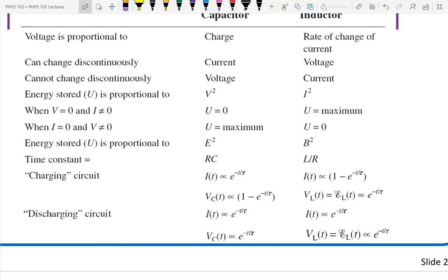So you have a capacitor that's really charged up. As some of you saw, you take that capacitor and you short across it once it's charged, and what happens? If you short it, what's the resistance between the two ends? Approximately 0. So what's your time constant if you have an RC time constant and R is 0? 0. So you have approximately no time constant. It discharges instantly.